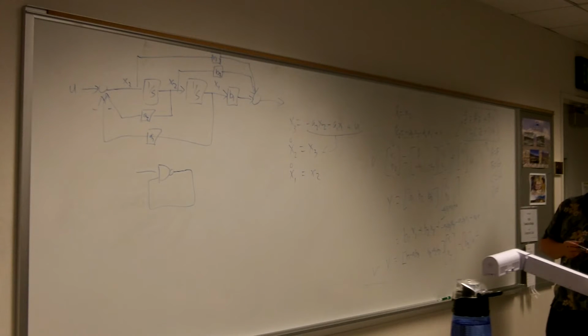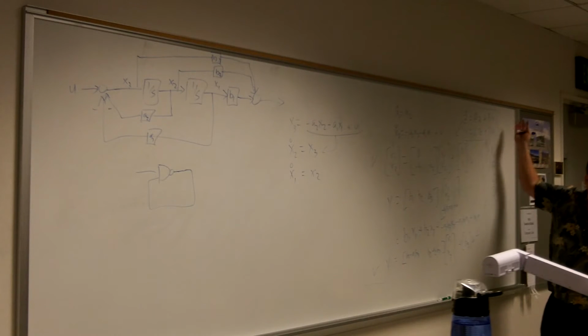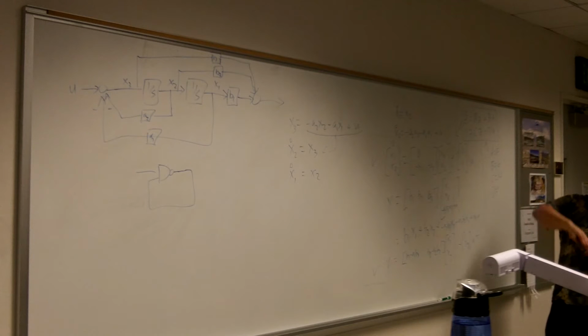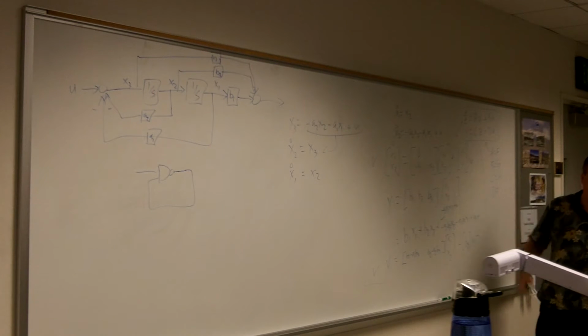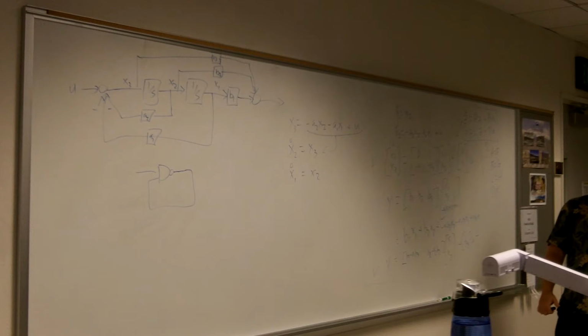That's a straight feed forward system. It really doesn't do anything, it just biases your solution. So whatever you prove for it without that, as long as your U itself does not go unstable, in which case you're screwed anyway. As long as it itself is bounded, it's going to have a bounded effect on the output because it never feeds back. It's just like adding a bias.